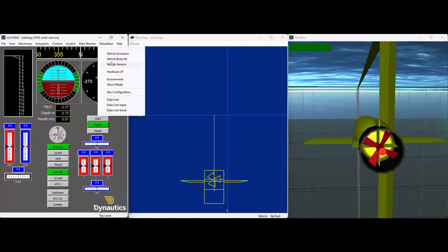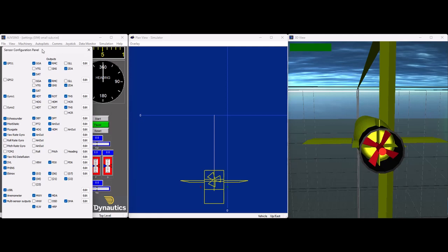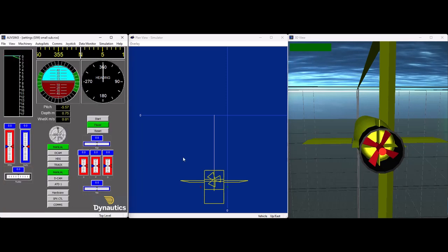Finally, the sensor fit. Well, that's similar to ShipSim. You select your sensors from the menu and make sure that the NMEA messages are enabled, and you've set up the error models and the position of the sensors as you'd expect. The method of controlling the simulator is again similar to ShipSim. You have the option to control it through a hardware interface or through a serial interface.